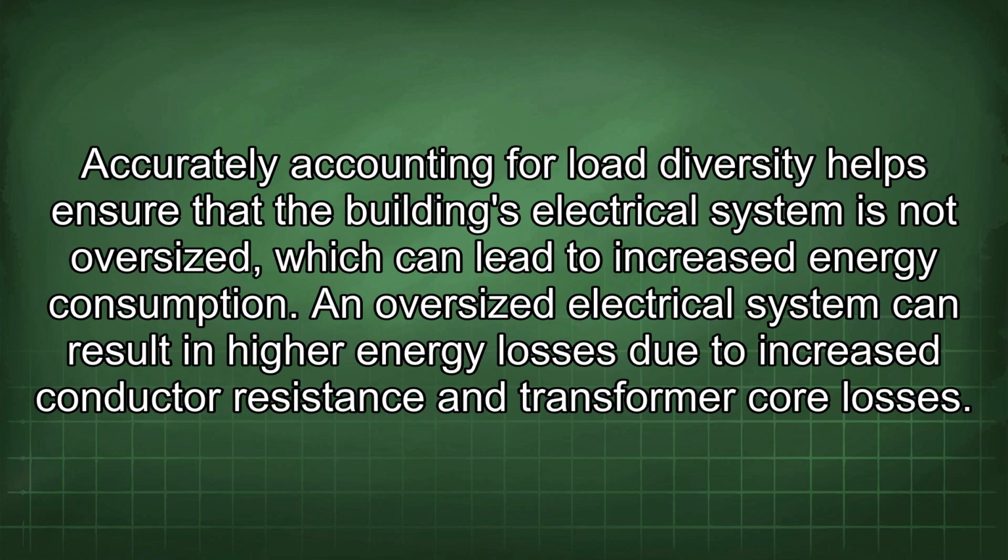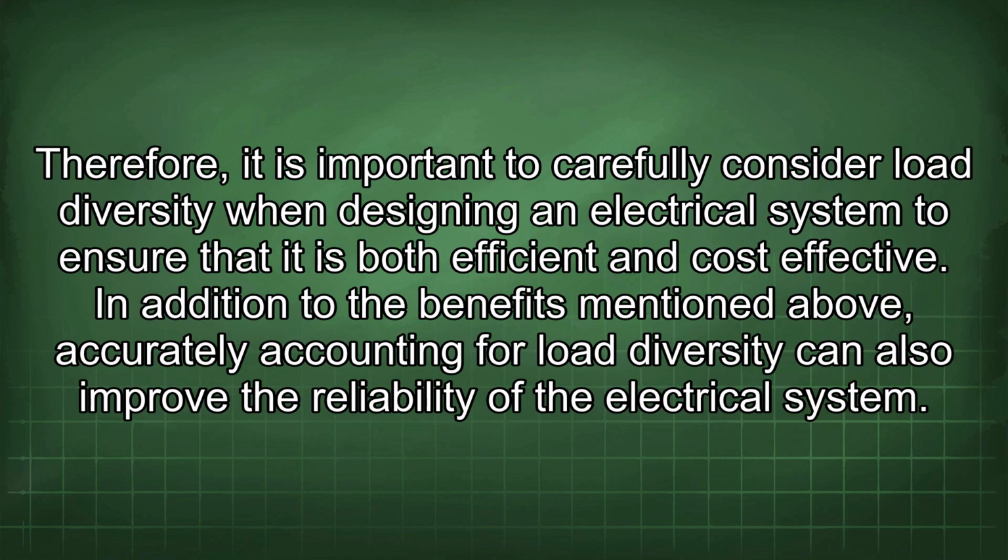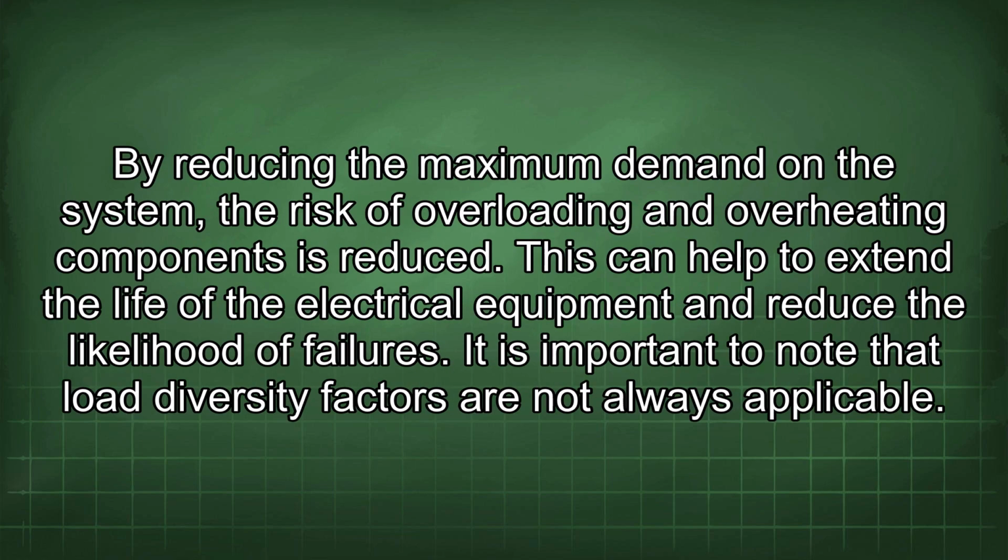An oversized electrical system can result in high energy losses due to increased conductor resistance and transformer core losses. Therefore, it is important to carefully consider load diversity when designing an electrical system to ensure that it is both efficient and cost-effective. In addition to the benefits mentioned above, accurately accounting for load diversity can also improve the reliability of the electrical system. By reducing the maximum demand in the system, the risk of overloading and overheating components is reduced.